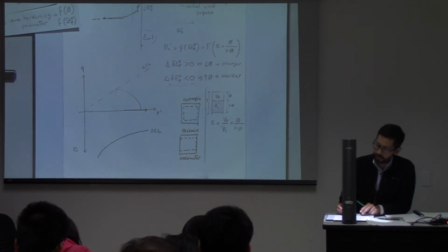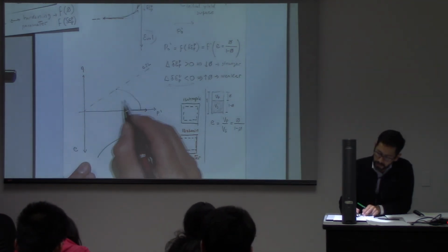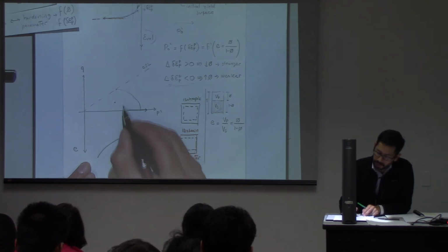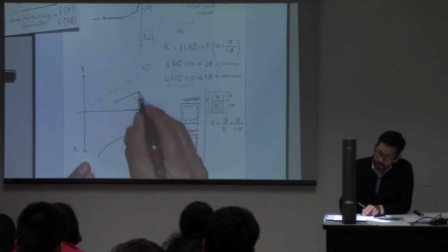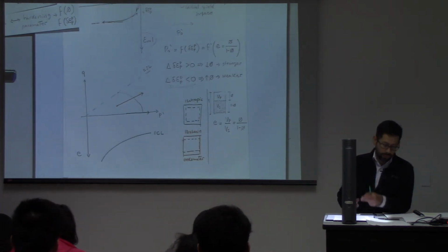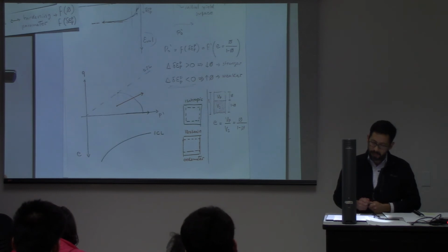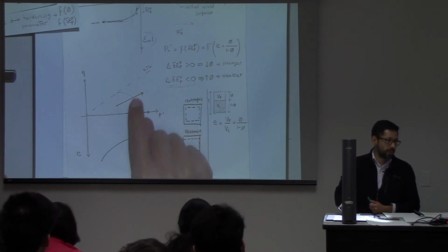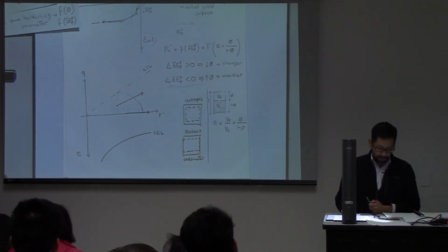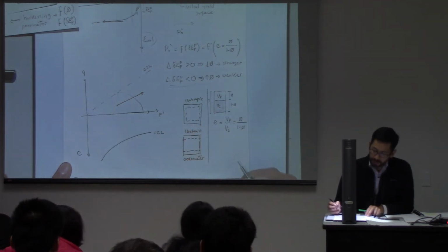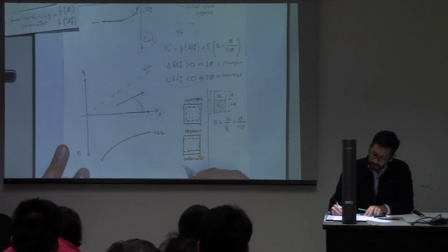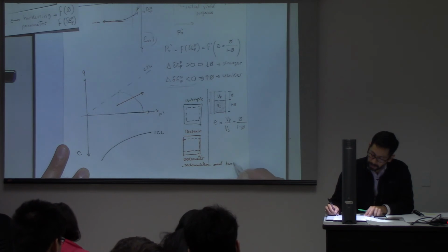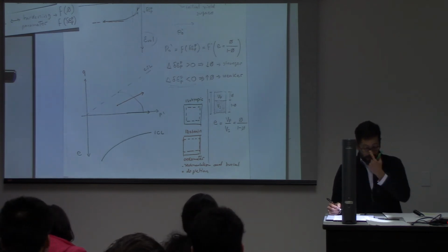And in this case, if you remember, the stress path will be a line that, let's say we start somewhere over here. It has a slope, and it crosses your surface somewhere at that point instead of at this point. So this will be closer, we said, to sedimentation and burial, or closer also to depletion. So that's a little bit more realistic.